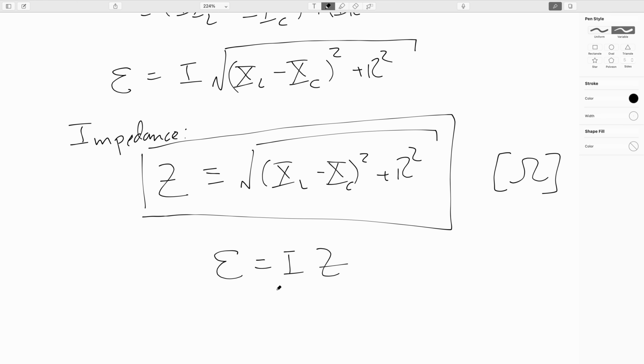So they're getting billed for the energy they would have used if their phase angle was 0. If their phase angle isn't 0, well then what will wind up happening is the company will be drawing more current than they need to, which is a waste to the power company.